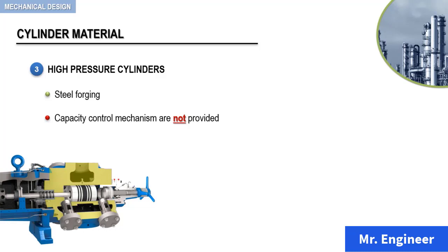Tie bolts may be installed perpendicular to the bore to pre-stress the forging, decreasing the maximum tensile stress induced by the gas pressure. Valve ports are finished to a highly polished surface, which reduces the maximum tensile stresses. In this arrangement, the pressure range for these cylinders is approximately 2000 to 8000 psi.